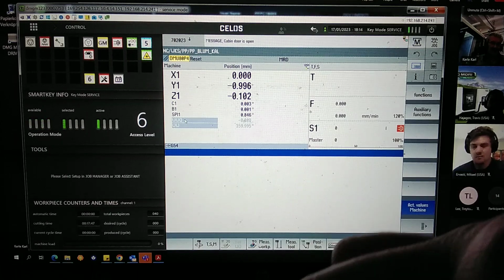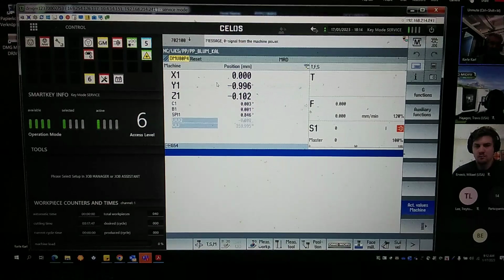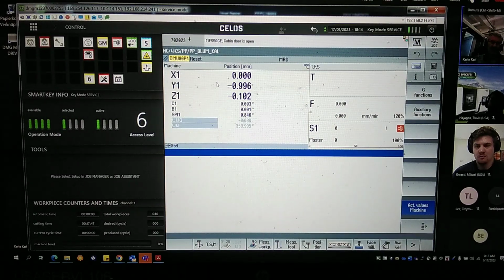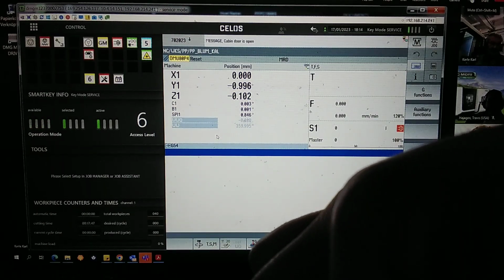The reason is that every value of change position is referred from the software to the machine coordinate system. Therefore, this is the only true indication for the whole range of change position adjustments, independent of tool changer, laser, pallet changer, or whatever else in that range. Okay? So far so good?